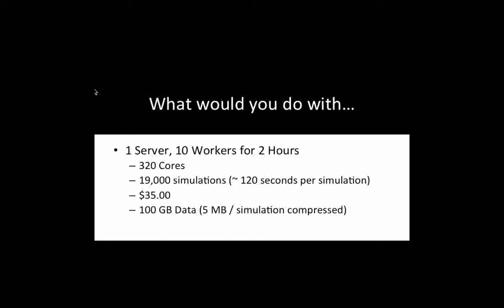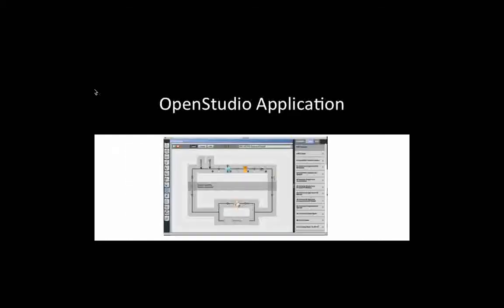These are basically the enabling technologies. OpenStudio is a big piece of this, and it's all based on open source software. So the idea is that you build your model via the OpenStudio application. You manipulate that model multiple times through these measures, which I've talked about. You can do basic parametrics via PAT. You can use that interface to stack up all your different measures, or build your parameter space basically. But then for really large-scale analysis, on the order of thousands of simulations, we really suggest that you use the OpenStudio Server product. This is a screenshot of the application.